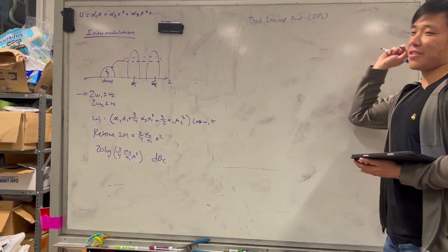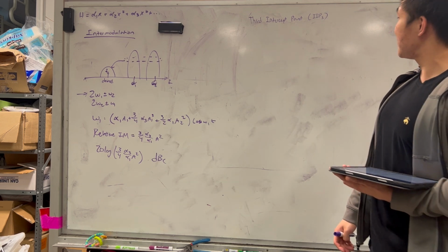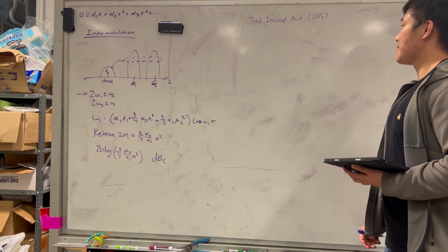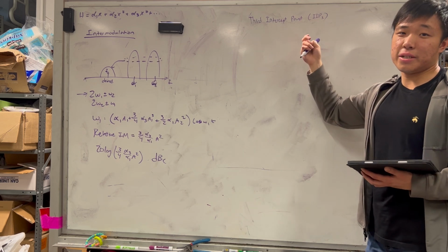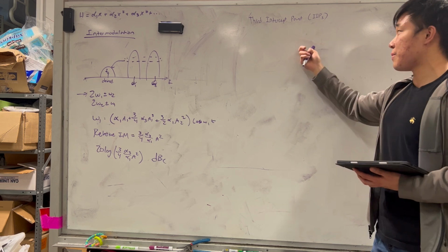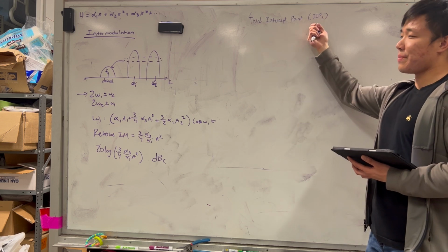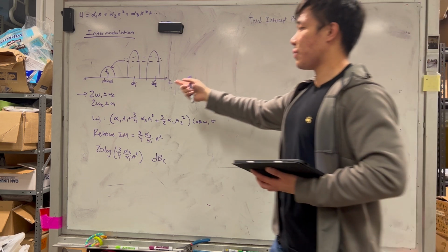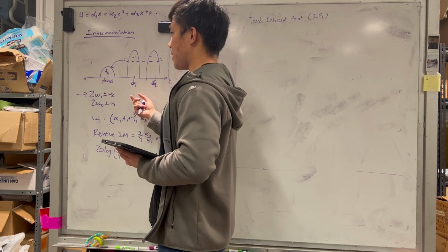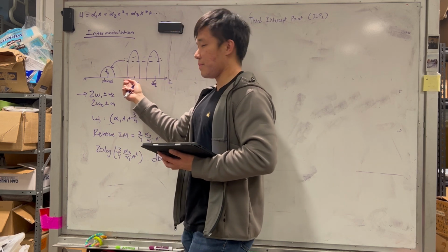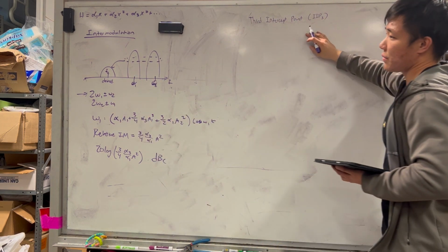You guys have probably heard this term if you've looked up some RF stuff in the past. In general, you can generalize this to IPN, but IIP3 is a very popular one. IIP3 and IIP2 are the most popular. IIP3 is more popular than IIP2 because typically when you're working with frequencies that are really close to each other, your IIP3 point would be very close to something similar to your signal, right? So that's why IIP3 is generally more important.